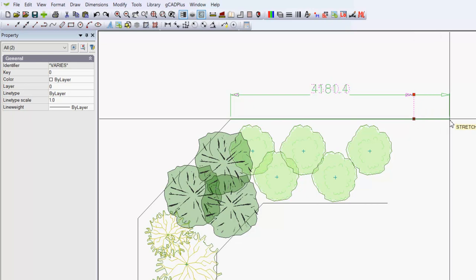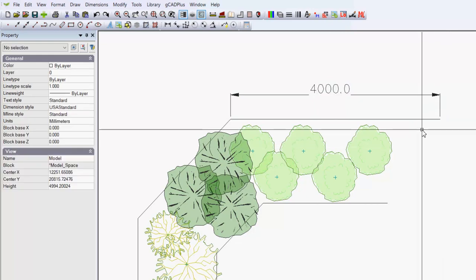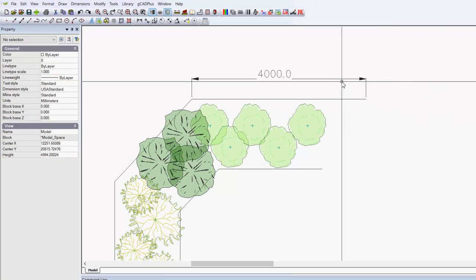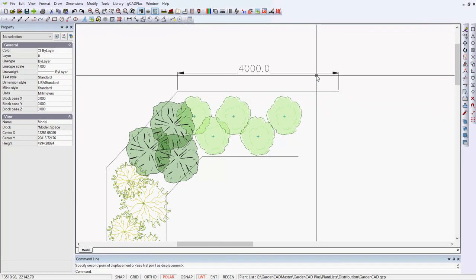So the database is all tied together, and I can type 500 and just hit enter, and both the line and the dimensions stretch with me. So the point of this little story is everything is full size, and you let the CAD software build the model full size, and then you can just take dimensions from the model or edit things quickly and easy. It's a very fluid process.